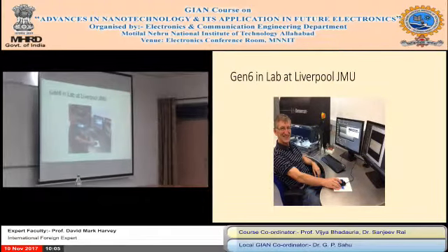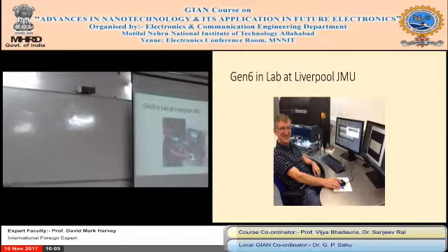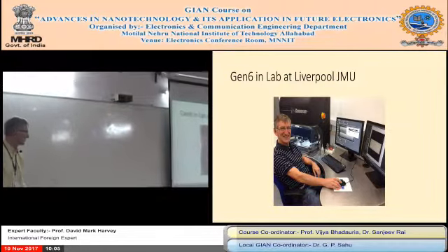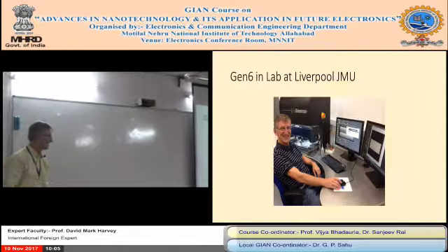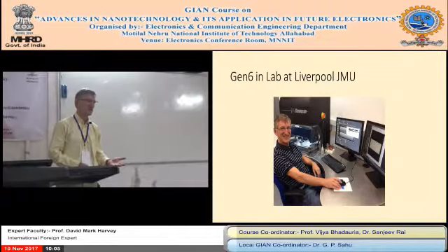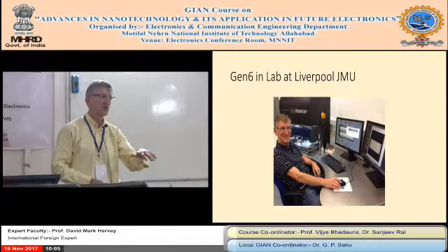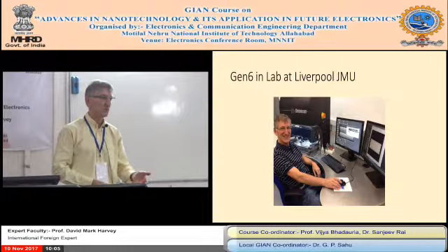So we get 2 screens. We have a scan screen and a processing screen, and we've actually developed our own toolbox to do the image processing, which I'm not talking about this week. But the trick is, again, this is hard to use. You need to learn how to set up the transducers, where to focus the transducers. The temperature of the water is important.